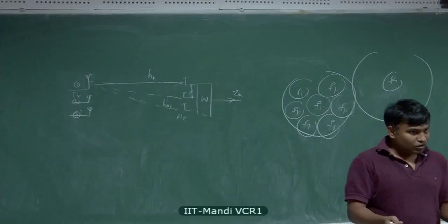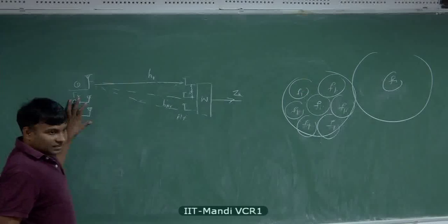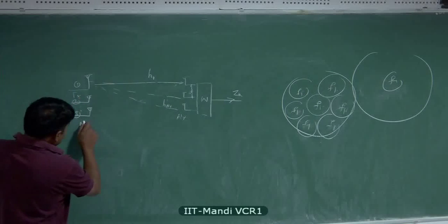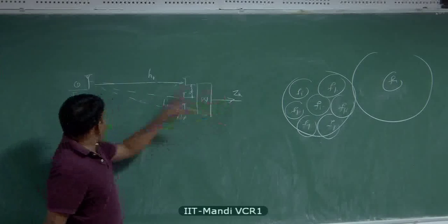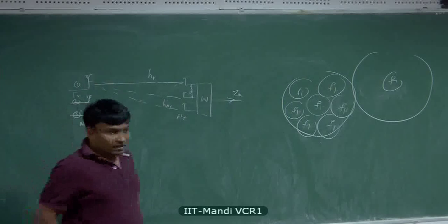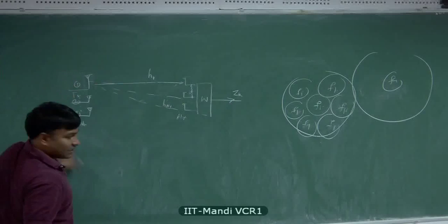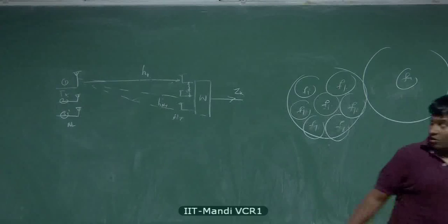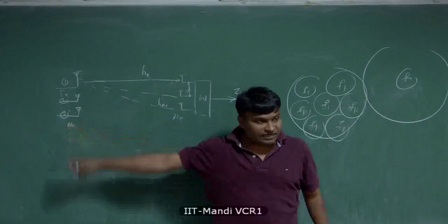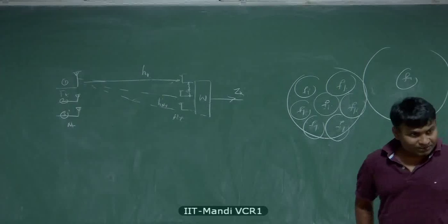They're coming from the same source, but it doesn't matter for this linear combiner. They all act as interferers, and you can reject interference using this linear combiner and detect the data stream 1 reliably. Similarly, you can detect the data stream transmitted from the second antenna by treating everything else as interferers. So you can have a set of parallel receivers to detect all the data streams 1 to whatever the number of transmitters, and that is one way of increasing the data rate. And this technique is called spatial multiplexing.